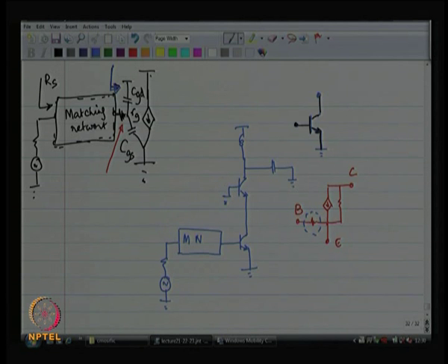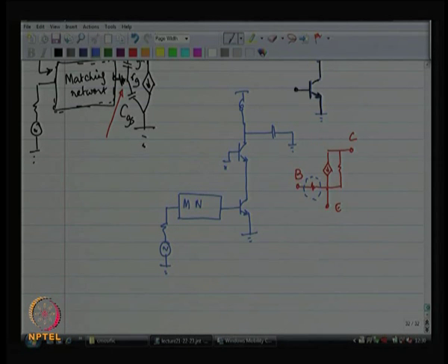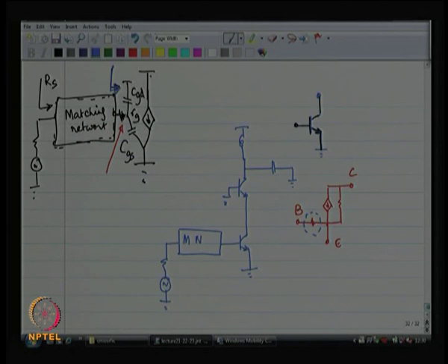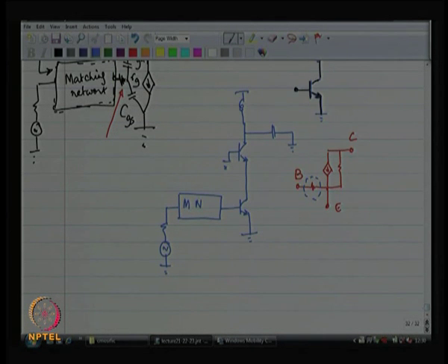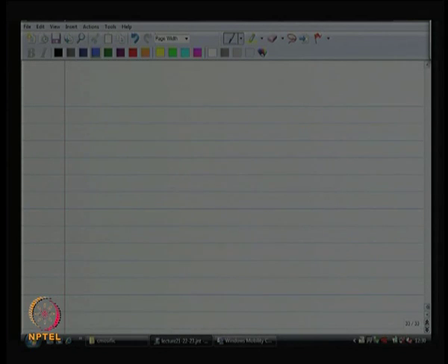Could have something like this, right. Here this base emitter, the resistance between the base emitter is not a physical resistance, it is not going to generate its noise, all right. So, you can make low noise amplifiers with BJTs as well.